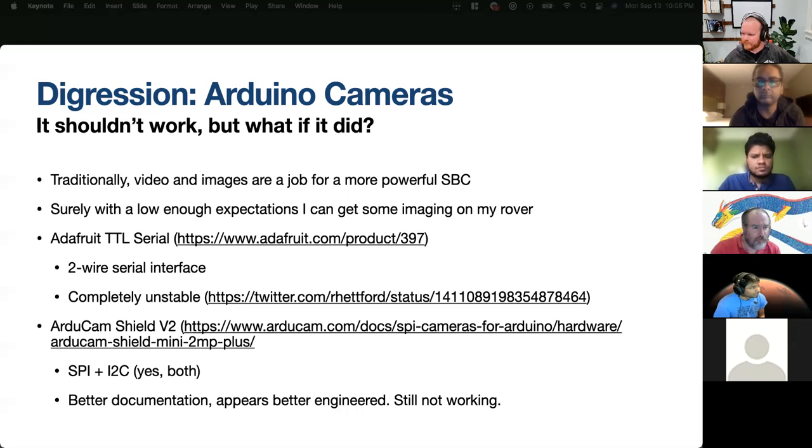Yeah, but SPI is a one-to-one device interface, and you cannot attach multiple devices without, let's say, a multiplexer on the SPI. I2C is multi-device, so you can have several devices on the same bus, but on SPI you can't. But the problem is I2C can't have as much speed as SPI. Interesting.